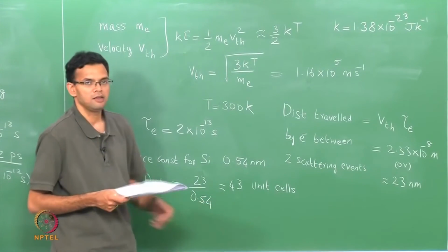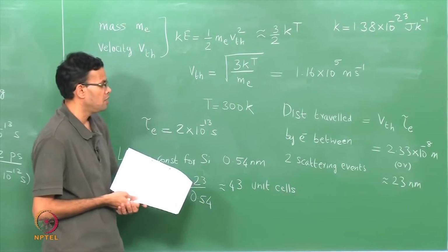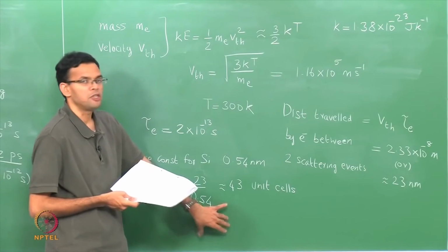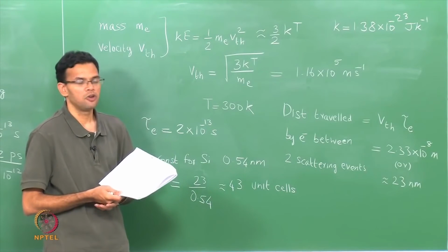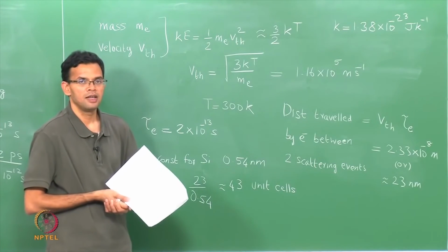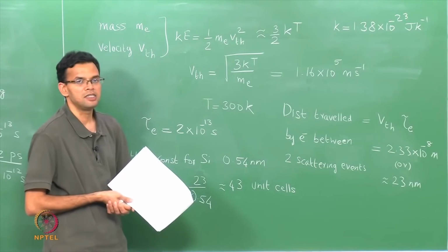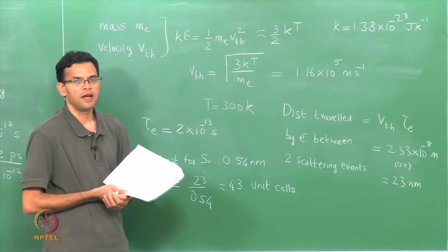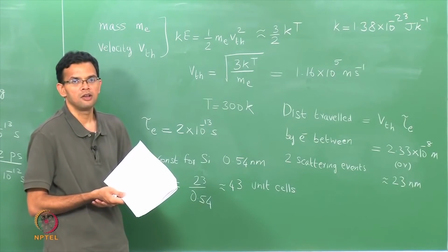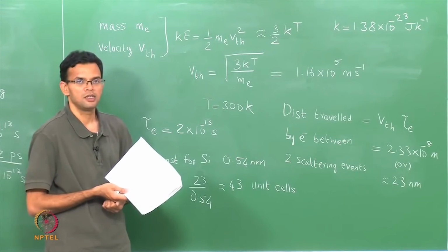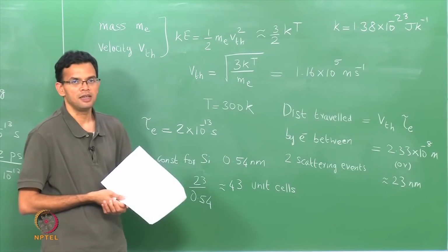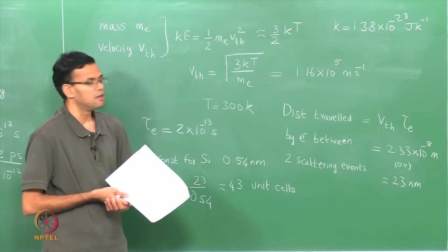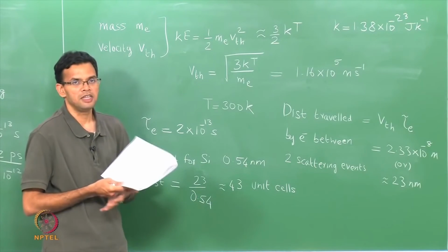Mobility is usually a function of temperature. It can also be thought of as a material property as long as you do not add any impurities. Later, when we look at extrinsic semiconductors, you will find that increasing the concentration of the dopants decreases the mobility. You can compare the mobility of silicon with some other semiconductors to see the values.